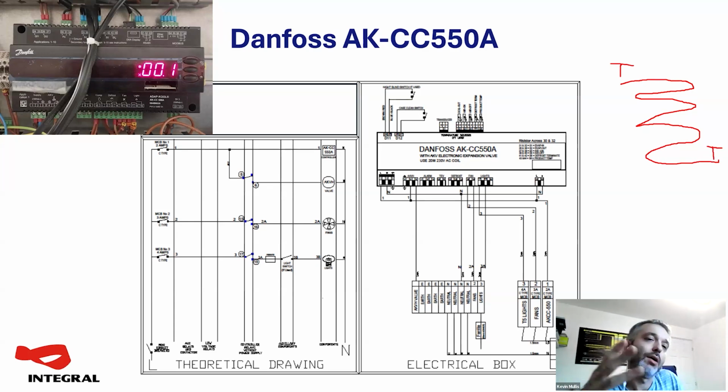Obviously, if anyone worked on the old precursors to this controller, you'll know that had a DC expansion valve on it. This has got an AC expansion valve. Key when you're changing the coil on site, if you've got one on the van that you've had for 10 years and it's a DC one, it ain't going to work with this. So be aware of the differences on that.